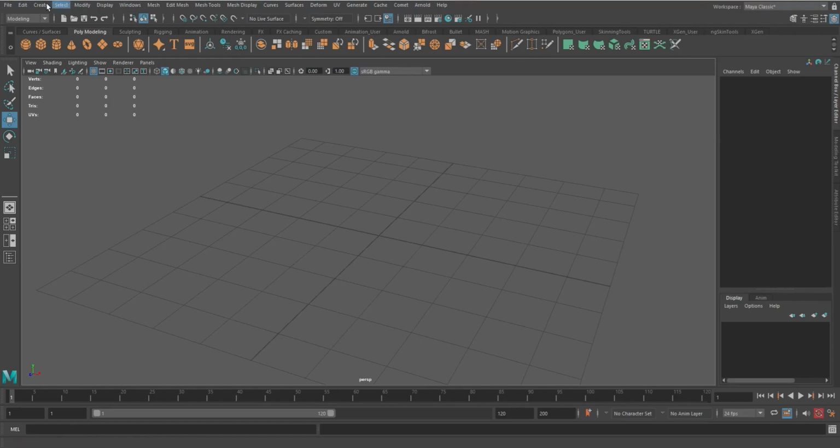This top menu set is where you'll find everything in the Maya tool set. You'll notice that from Windows to the cache is going to be based around different modules. With modeling, you'll see that mesh to generate is all located in the modeling tool set. If I change this on the left-hand side to rigging, you'll see that from Windows to cache, now we have skeleton, skin, deform, constrain, control, and these are all very specific to rigging and animation as well. Now this is the animation tool set: playback, key, playback, audio, visualize, deform, constrain, and the mesh network.